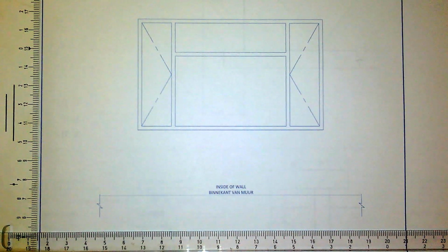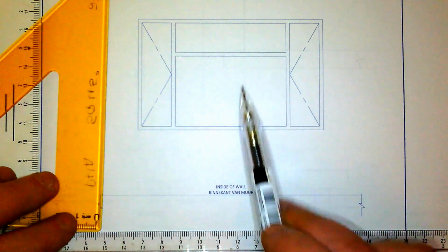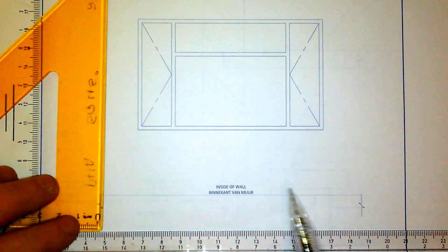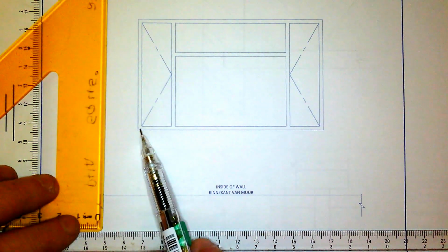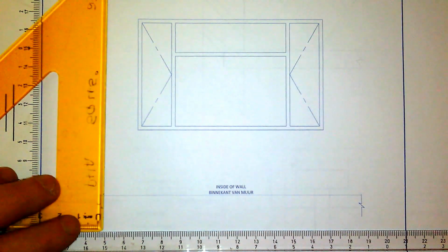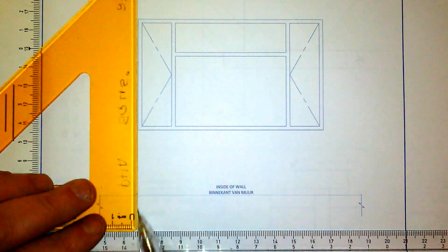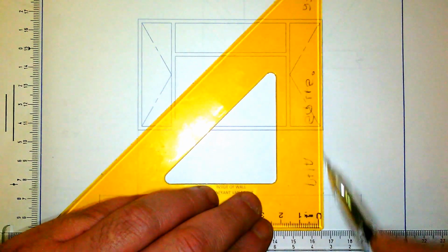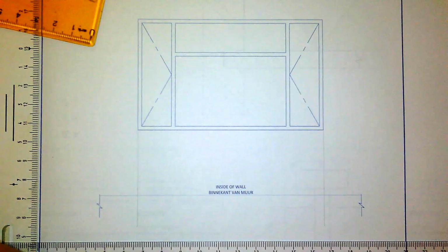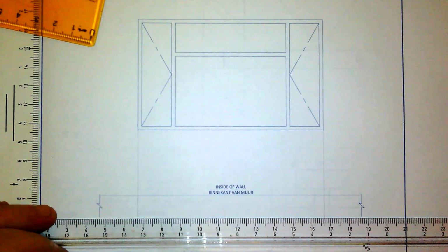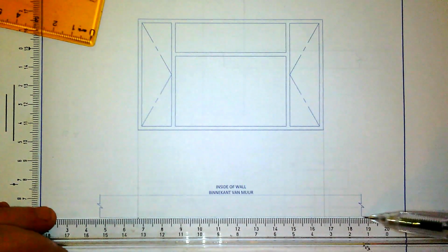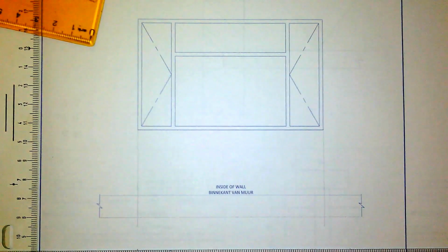So the instructions actually say to draw a partial plan that will show the window in an external wall. So it's a partial plan because we're only doing one window and nothing else. Okay, so all you have to basically do is take the length. Now normally in the exam you wouldn't have this above that because it would be part of a much bigger plan, but you would go to the diagram that I supply and you take that length and you mark it down. In this case we can just project it and you mark down the length on each side. Okay, like so. And then all you have to do is also to mark down the thickness of the wall. Okay. And then you have to know which side is inside or outside.